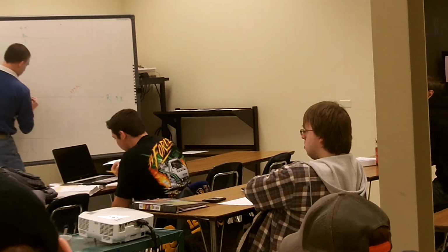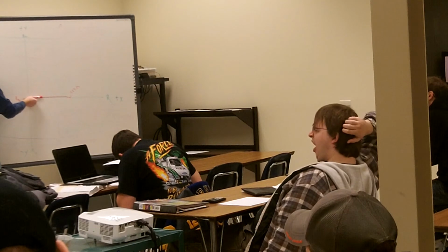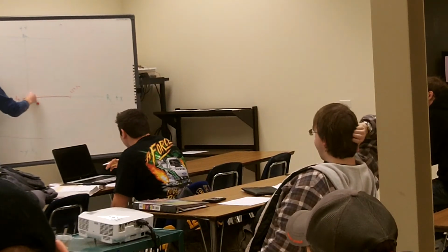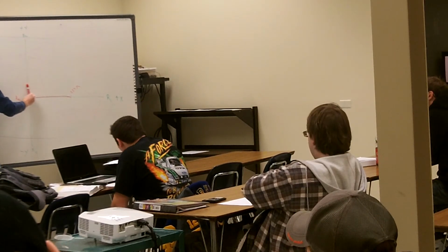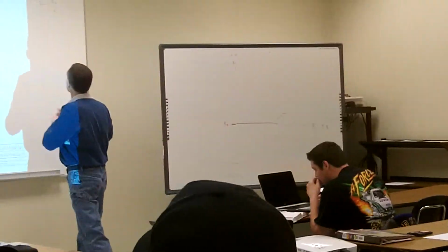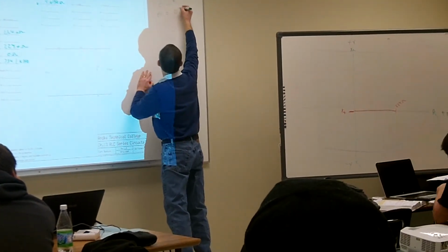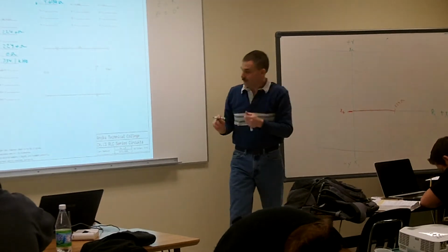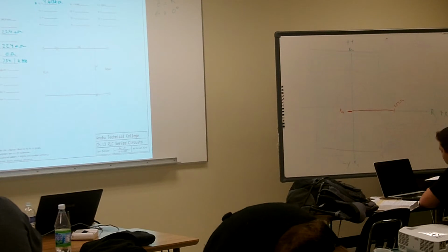So let's continue on with our phase angle then. We know that my Z is here. So what's my phasor angle going to be? We know that this is going to be a negative 90. This is a positive 90. What is it right at this point? 0. So then that's another thing: my theta is always going to be equal to 0 degrees at my resonating frequency. Those are all the things that are going to happen at my resonating frequency.